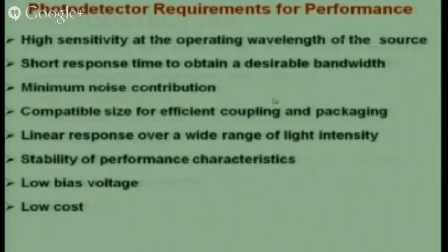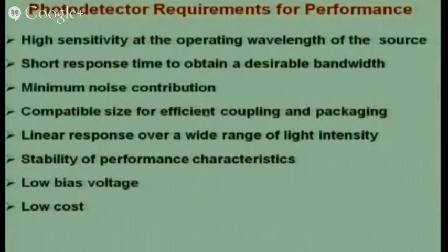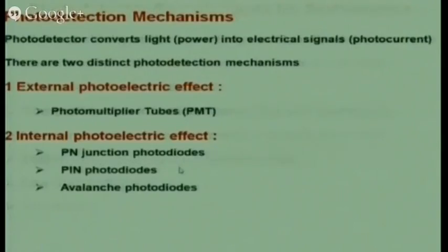So again, we have to look for requirements: it should have high sensitivity, short response times, and noise consideration, that it should give me minimum noise. It should have a compatible size, that means I should be in a position to couple this to the fiber, linear response, stability, low bias voltage, and low cost.